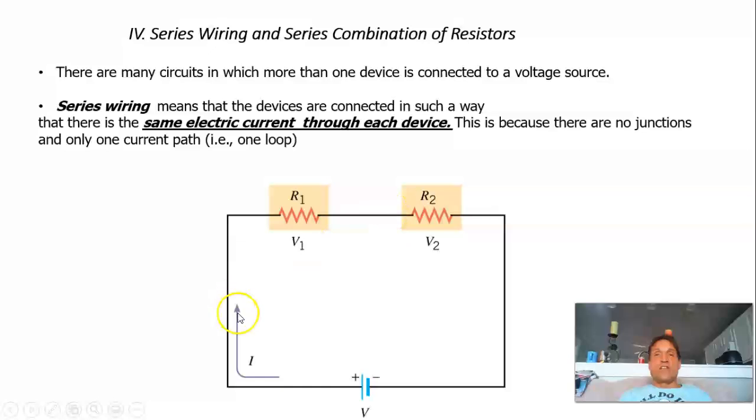Bigger resistance, less current, same total voltage. The power consumed by the circuit decreases. So the more things you hook up in series, the more your total resistance becomes, the less current your battery supplies, and the less power your battery supplies to the circuit. Your battery will last longer.